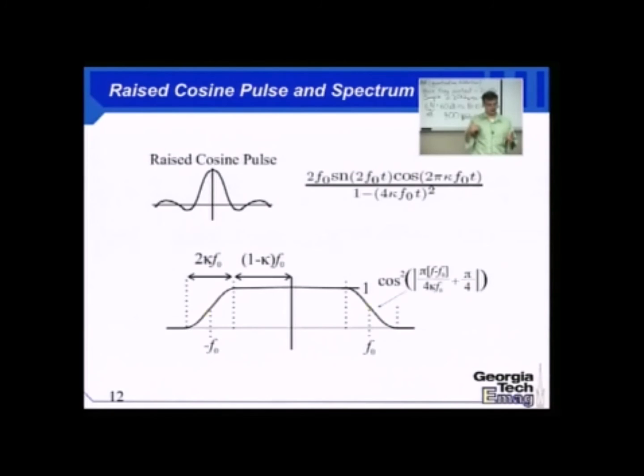As part of the homework exercise online, there's a spec written very similar to how the FCC would require a wireless spec to be written, saying it's using the ISM band. Here's the ISM band. Make a pulse that fits within the 80 or 100 megahertz of spectrum about 2.4 gigahertz, and is 50 dB down from your peak value outside that spectrum.